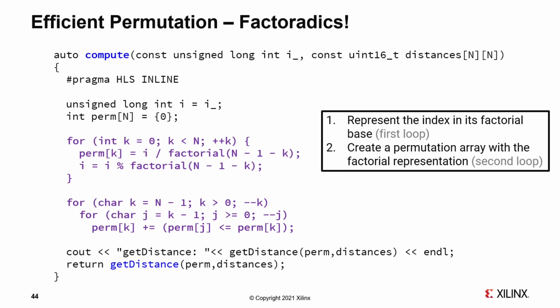The code describes quite a few operations, but notice that the data types are limited to integers and char for the loop index. These are very efficient data types for an FPGA, more so than manipulating floating point numbers, and for this section of the code, there is no need for floating points anyways.